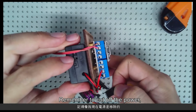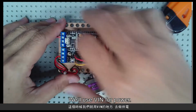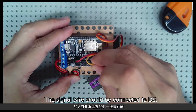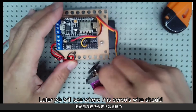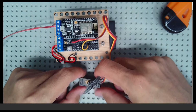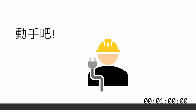Remember to cut off the power. My power is turned off. We'll use VIN for power. The signal wire should be connected to D5. Later we will see where this servo's wire should be connected. You can try it out yourselves.